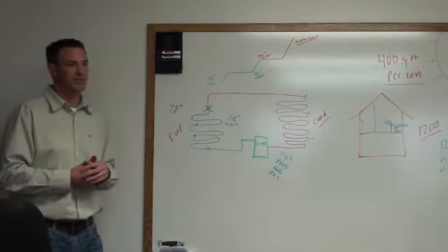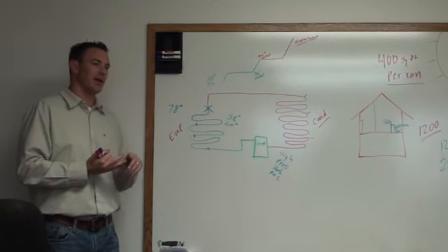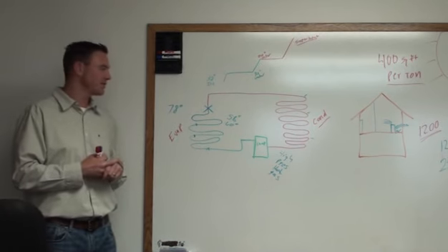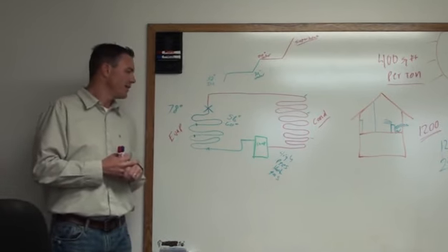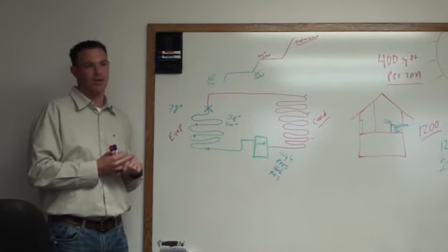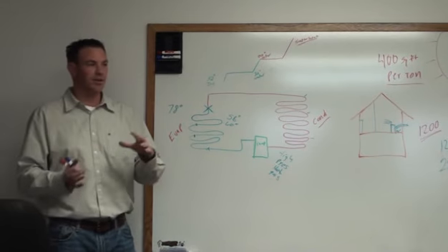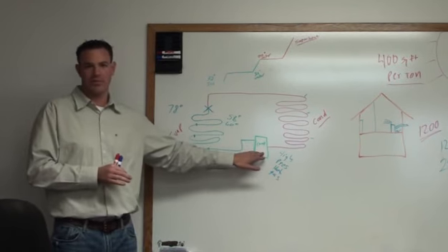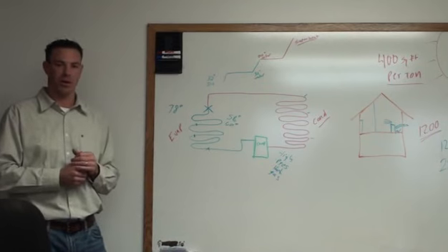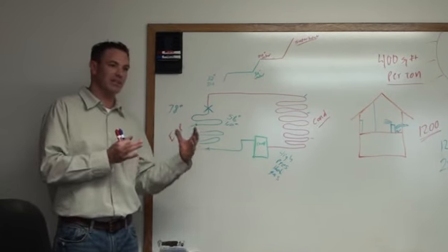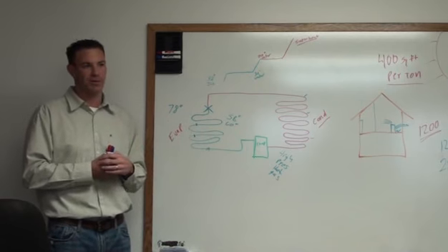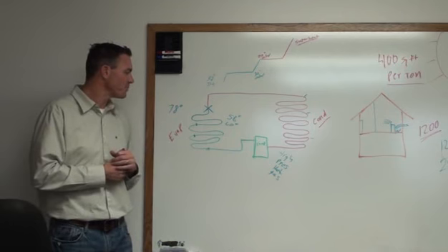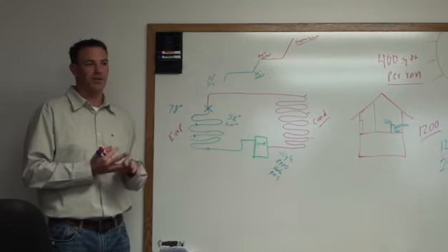A couple more things that I'll just brush on without getting too in depth. Compressors. Compressors are really expensive. They're essential for the operation of the air conditioning system, and they're pretty touchy. Okay, so if you get an air conditioning unit that comes and it's been tipped on its side, it has oil in it to lubricate the moving parts. Most likely it's going to have a problem. So we need to leave the box and the air conditioner sitting upright for at least 12 hours to let the oil get back to where it should be. Airflow, all of those kinds of things.